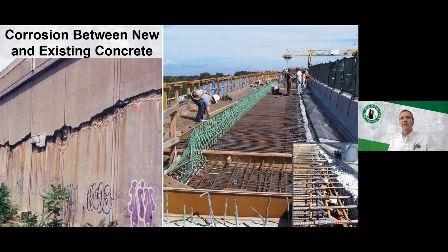To prevent that kind of problem, the bridge in the right-hand photograph here, this is a marine bridge. They are widening the bridge and adding a lane on the side of the bridge, and they have this interface between the old concrete that's 20 to 30 years old and partially chloride contaminated, and what will be the new concrete. And to mitigate this local corrosion effect that's likely to occur along the interface, they're simply putting in a line of anodes close to the edge.